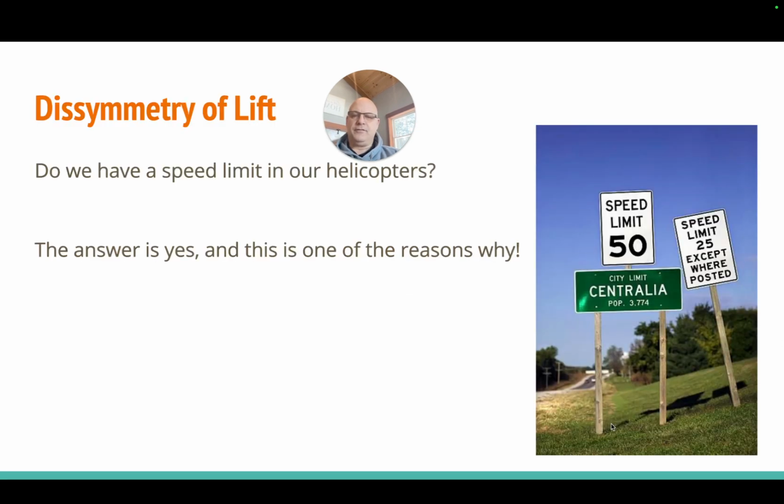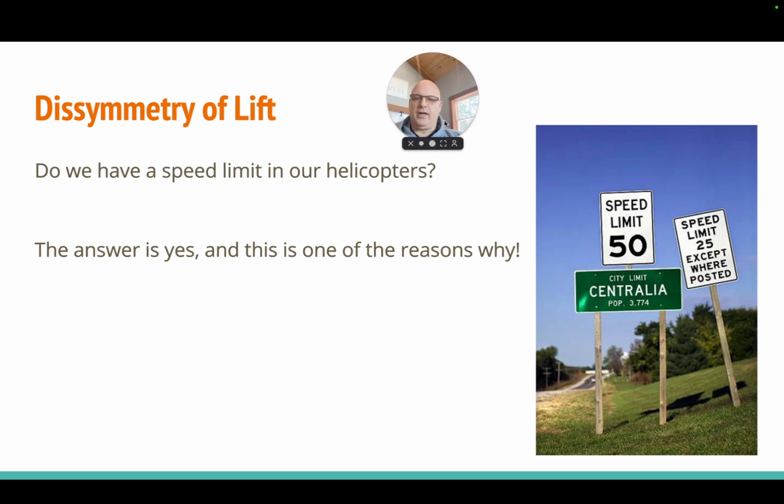We talked about the components of the aircraft itself, about the main rotor blade system, and we started understanding each of the components and what they do. So if you go up to the rotor mast again, go outside, climb up the aircraft, touching, feeling, seeing is the way to learn best. We have talked about the flapping, the hinges, the pitch horns, how the swash plate, the upper part, the lower part, all works in connection to the tubes that connect you to the cyclic and the collective, and of course the tail rotor to your pedals itself.